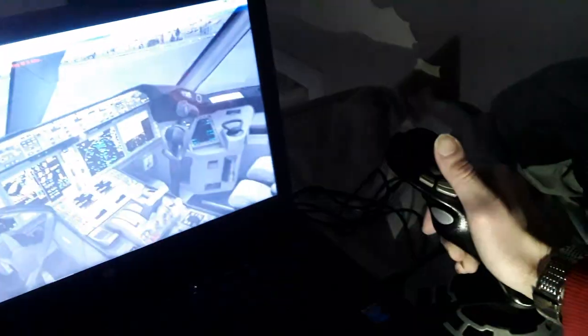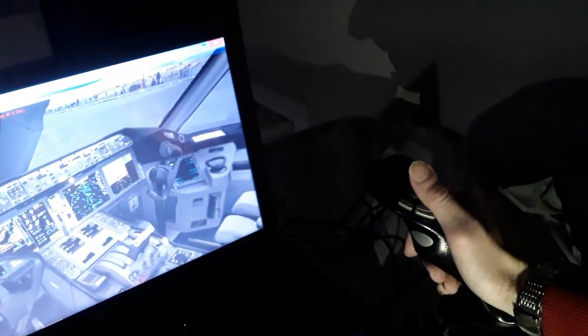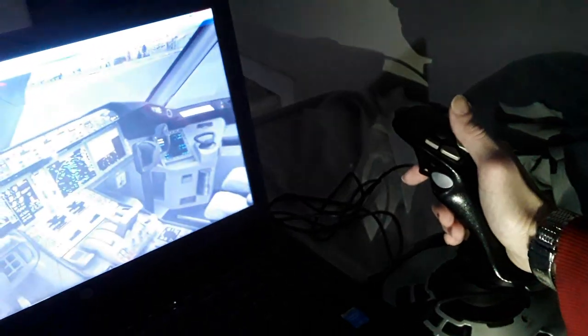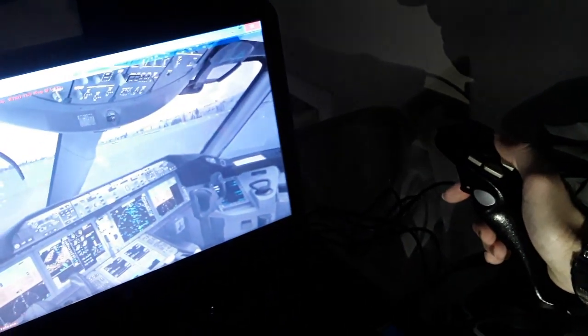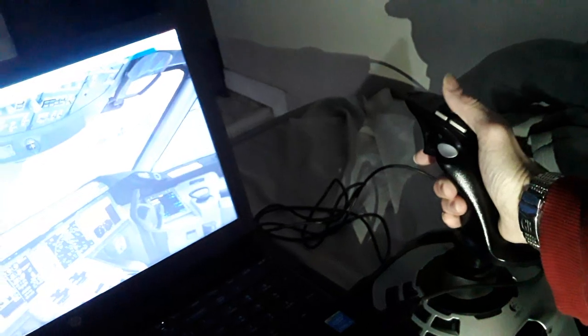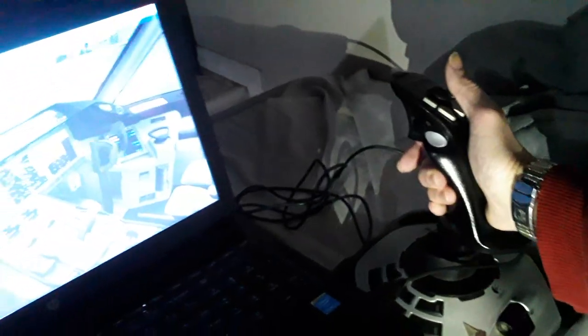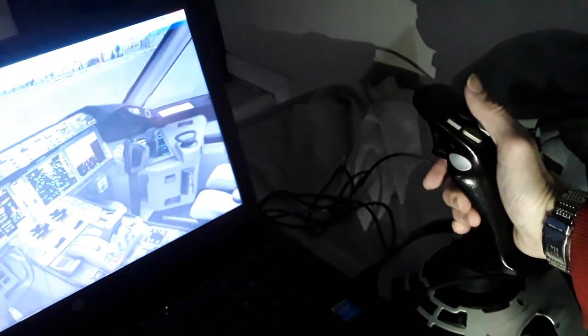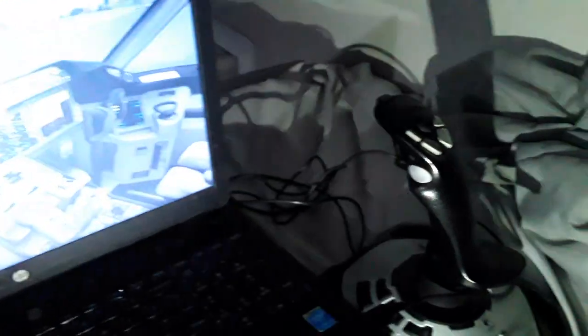Also when we release the side stick at maximum deflection from 67 degrees, the computer will return the aircraft to 33 degrees bank angle, either left and right. Also we need to input more side stick to level off and hold 1G in flight. So this is some of the flight control computers which control the Airbus aircraft, Airbus A320, A330, A340. Also the Boeing 777 and Boeing 787 aircraft have similar flight control computer inputs.